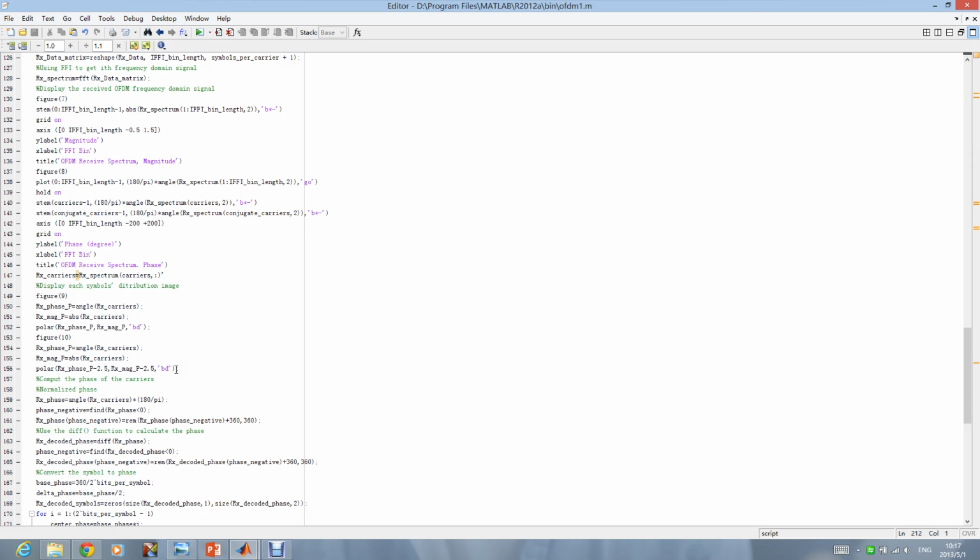And here we're going to say that we used MATLAB to simulate and show the signal after QPSK modulation. After the modulation, if the CP is much smaller than the delay in the channel, there may be no distortion in the signal.